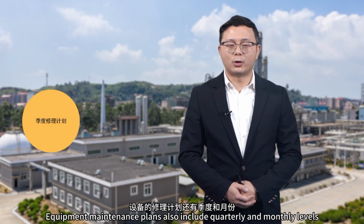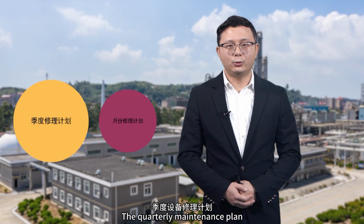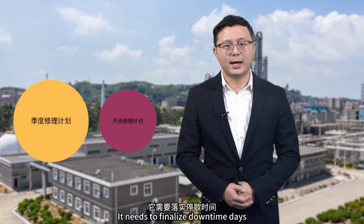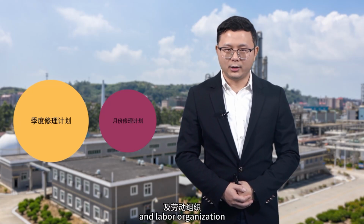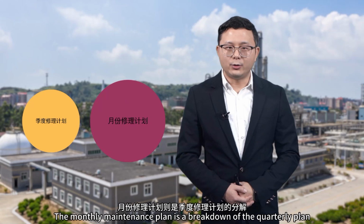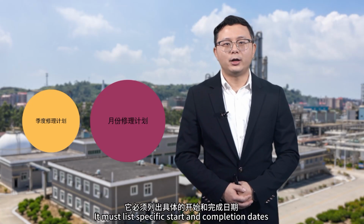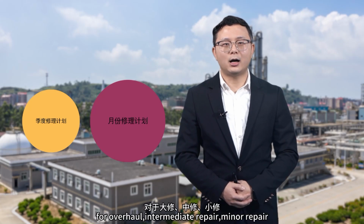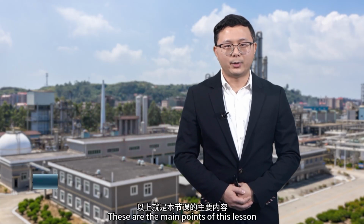Equipment maintenance plans also include quarterly and monthly levels. The quarterly maintenance plan is the implementation plan for the annual plan. It needs to finalize downtime days, repair technology, production preparation work, and labor organization. The monthly maintenance plan is a breakdown of the quarterly plan. It must list specific start and completion dates for overhaul, intermediate repair, minor repair, and installation projects to facilitate work organization. These are the main points of this lesson.